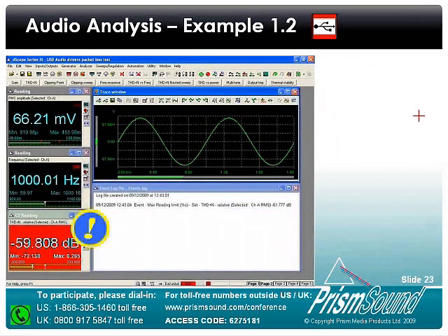One of the really interesting things that we're going to take a look at, and one of the powerful tools that we have inside the D-Scope system, is the ability to look at signals and analysis results over potentially indefinite duration. We have a tool called the Event Manager that allows us to look for intermittent problems. And when we're talking about a USB powered or a system that incorporates USB audio interfaces, we may be interested in looking at its stability over time and whether we're suffering from any packet loss problems or any other associated USB timing and data issues.